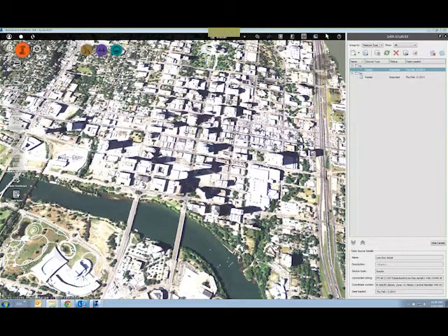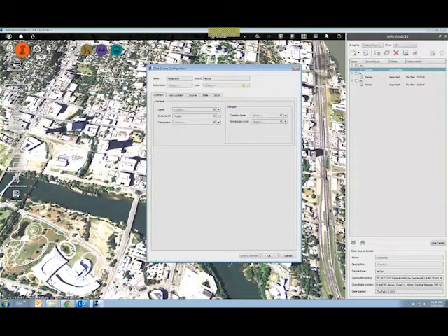So this is a GIS footprint of downtown Austin, and this time, because it's a shape file, InfraWorks says, well, it could be any number of things. So how do you want me to classify this data? How do you want to work with this data? And these are building footprints, and I happen to know, because it told me on the City of Austin website, that they have the roof elevation coded in this data table.